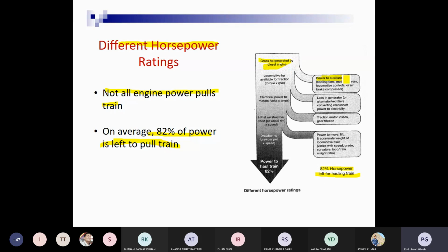So the traction power is lost in the generator, meaning the alternator or the rectifier bank of capacitors. That means converting the crankshaft power, efficiency, a lot of machinery is there. So magnetic loss will be there due to hysteresis and eddy current loss. Crankshaft means it is used for compression. In the compression you are using, for pantograph uplifting and downlifting, in both cases you have to use what is called a baby compressor.